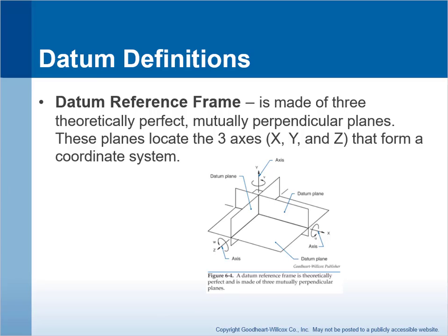a degree of freedom is the part can move along this x-axis in either direction. The part can move along the y-axis, in this case it's drawn up and down, or along the z-axis. And then those are the translational. Now the rotational degrees of freedom are shown here. This is this W here, so that you can rotate the part about that axis. All 3 of these axes. X-axis has a rotation, y-axis has a rotation. So these are essentially the degrees of freedom.